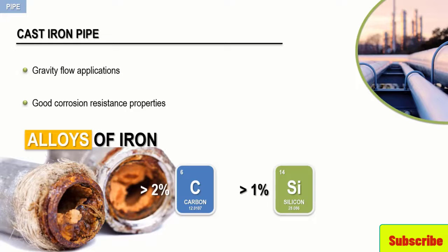In steel, this graphite content does not exist, and the compounds created during corrosion cannot bond together. Unable to adhere to the pipe, they flake off and expose an unprotected metal surface that perpetuates the corrosion cycle. In tests of severely corroded cast iron pipe, the graphite compounds have withstood pressures of several hundred pounds per square inch, although corrosion had actually penetrated the pipe wall.